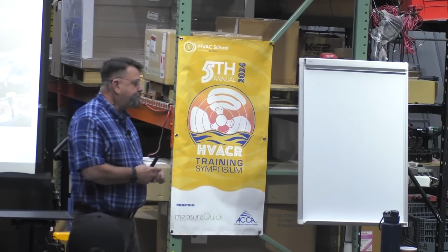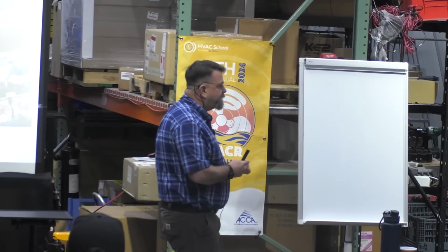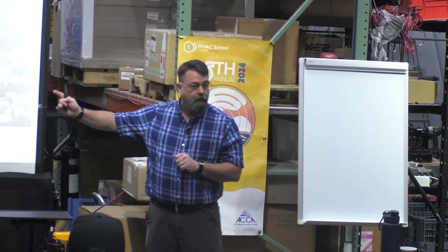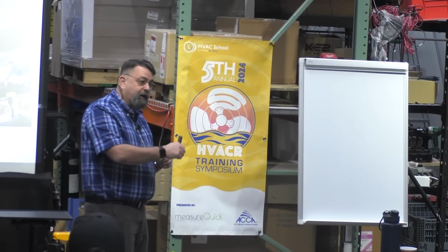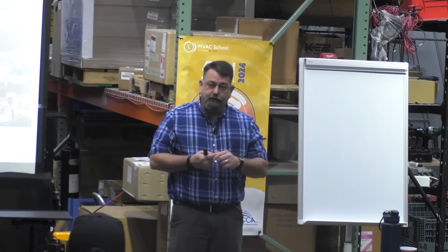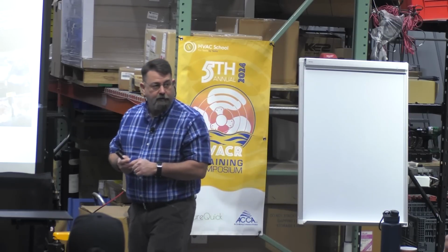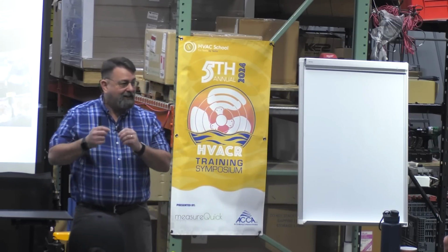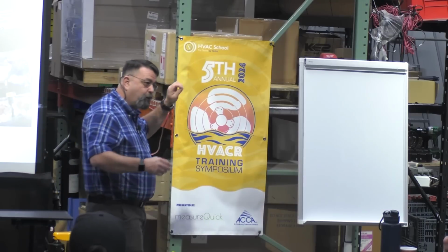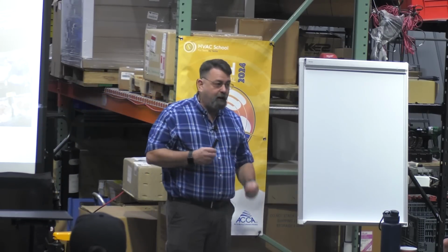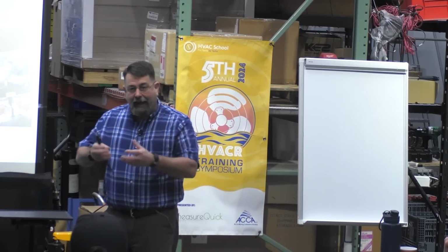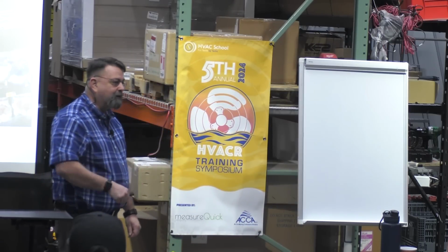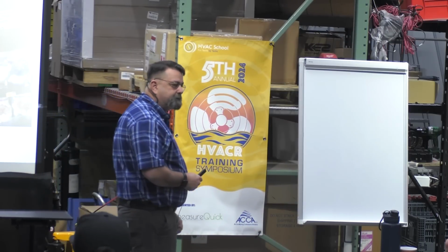Follow up on that. And really understand the physics of this refrigeration cycle, because I got a lot of pipe out there and I have no way to look inside that pipe. I have a pressure gauge, I got a temperature gauge, and that has got to tell me what's happening inside. That means I have to understand the physics of what's supposed to be happening, right? Am I at saturation? Am I superheated? Am I subcooled? What does that mean? How do I measure it? Is that what's happening in this pipe, right? Make sense?